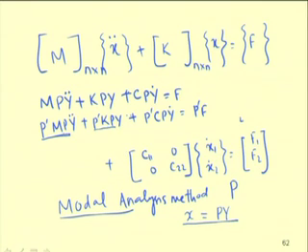So, the whole system can be reduced to a diagonal mass matrix, diagonal stiffness matrix and diagonal damping matrix. The equations will be uncoupled and these uncoupled equations can be used to find the solution of the system.